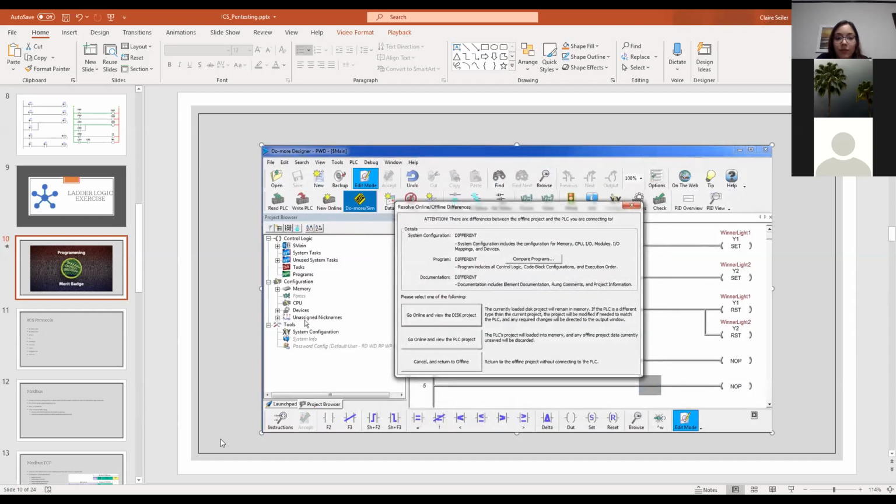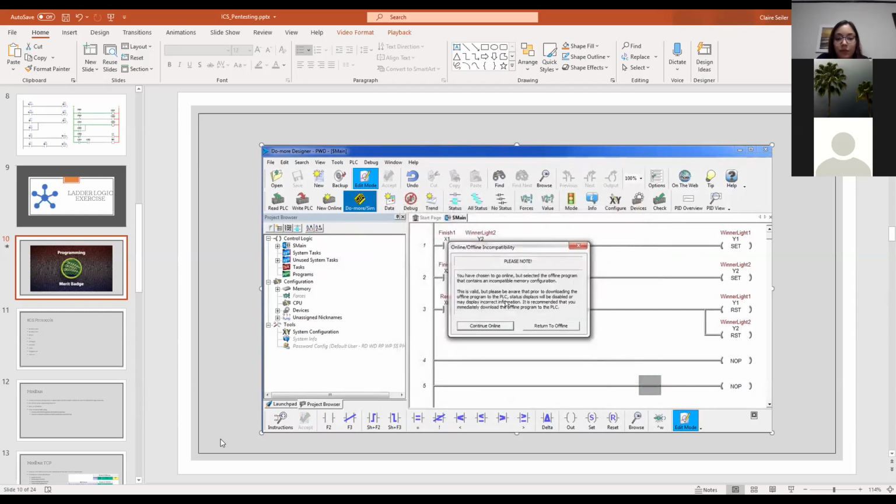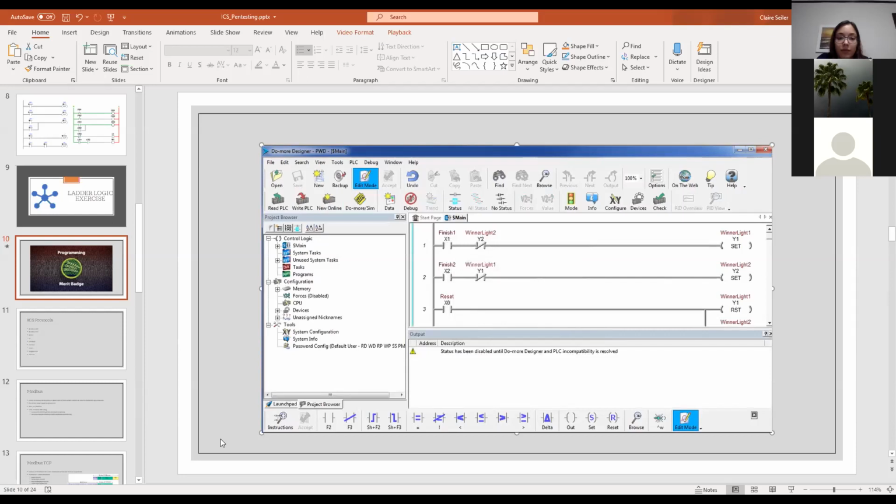And it's asking us, what do we want to do? Do we want to go online with this PLC and view our disk project? That's this guy right here. Do we want to go online and view what's currently in the PLC? No, we don't want to do that. Do we want to cancel? So we want this guy. And it's warning us, saying, hey, the PLC does not have this program in it yet. Yeah, we know that, so let's continue. And we're ready to go.